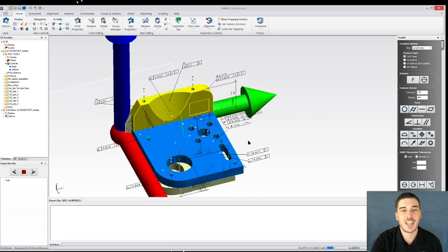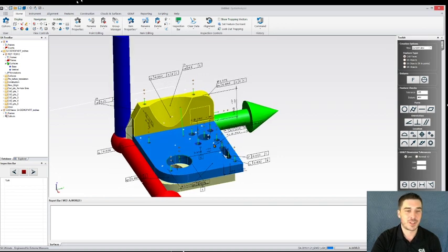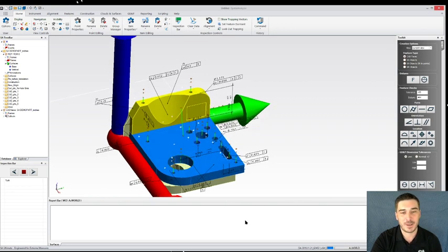And if you're using a CAD model that has annotations built in, that's the great thing is all the CAD translators are included. So just drag and drop them right into the software and you'll get your annotations there. Now with GD&T in SpatialAnalyzer, the annotations are the first step. Those are going to actually define the checks that need to happen. And they're going to show you what surfaces those checks happen with. So if you have annotations, you're already most of the way there.